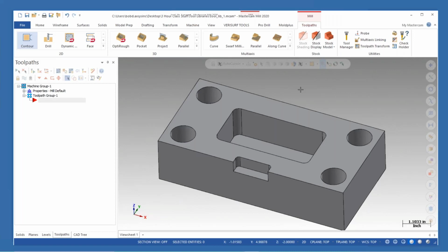So if you think about that, about 15 seconds per tool, and let's just say I've got 10 tools per job. This job, I've got a few less, but on average, let's say 10 tools. That's 150 seconds that I spent. And let's just say I do 20 parts a week. That's 1,500 seconds. And if I multiply that out over a year, it's 43 hours. 43 hours I've spent defining speeds and feeds and bringing in tools that I can do ahead of time, so it takes 1 or 2 seconds to bring those tools in.